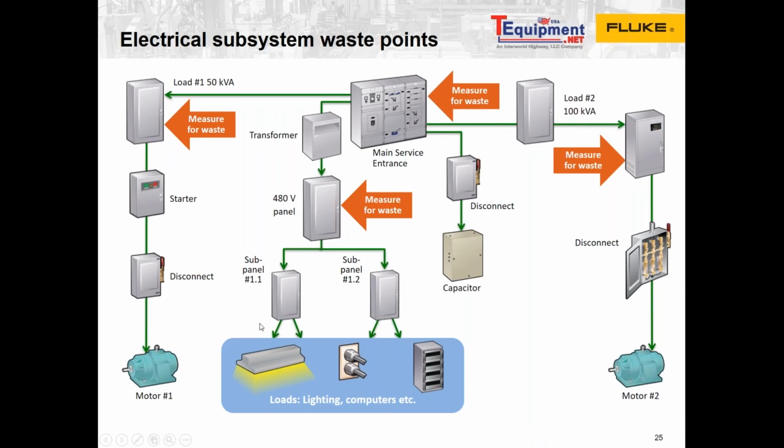The other one, which is very common, we've brought up a couple of times already, is if you measure here at the sub panel, maybe this sub panel is dedicated completely to lighting. You can see how much energy your lighting system uses. So then that will justify, hey, maybe in this case, we'll switch out the numbers. The lighting is actually using 60% of our energy. And guess what? They're those older style fluorescent bulb lighting. Well, if we go to LED lighting, this is how much money we'd be saving. Same with anything else like servers or your printers or computers and whatnot.